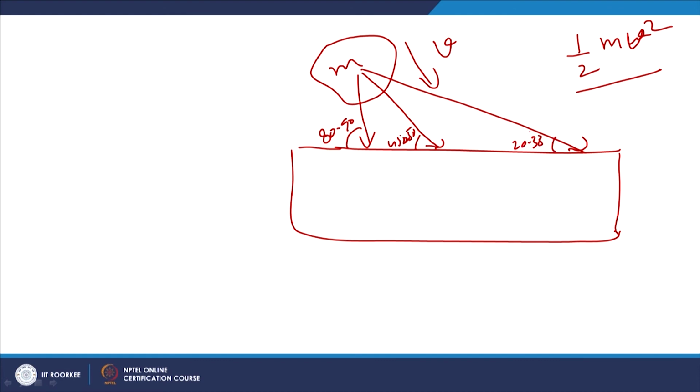So, these are the three angles at which this particle can impact, or it can impact at other angles also, but it can lead to different ways of material removal from the functional surface being considered, and the severity of the impact will also change with the angle of impact. Whenever it impacts, depending upon the kinetic energy associated with the impinging particle or droplet, it will cause some kind of damage to the surface.